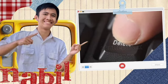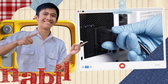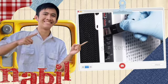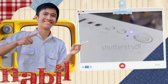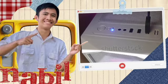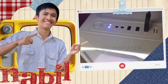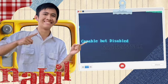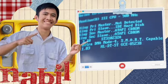Step 12. This is the moment of truth. Plug in your monitor, keyboard and mouse. Connect the power cable to the power supply and flip the switch on. Press the power button, your system should light up and spin all fans. Enter the BIOS by pressing Delete or F2 during startup. Check if all components are detected, such as CPU, RAM, storage devices, GPU. If everything looks good, proceed to install your operating system such as Windows or Linux via USB.